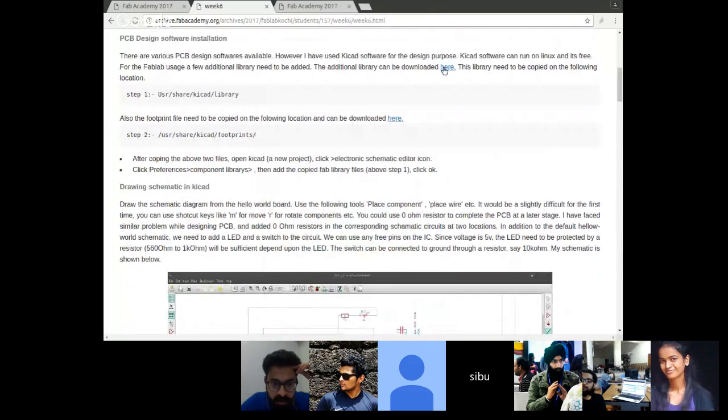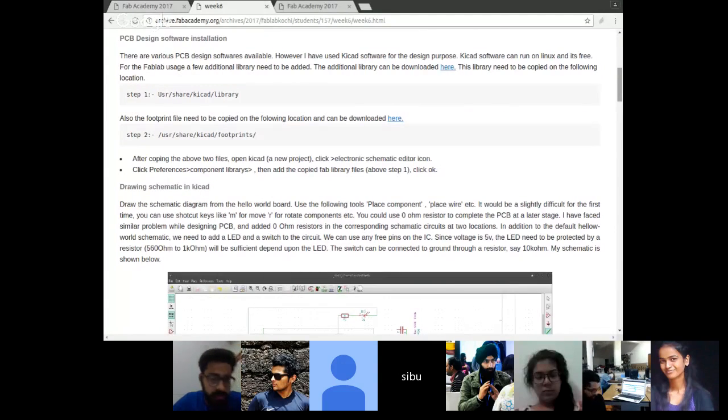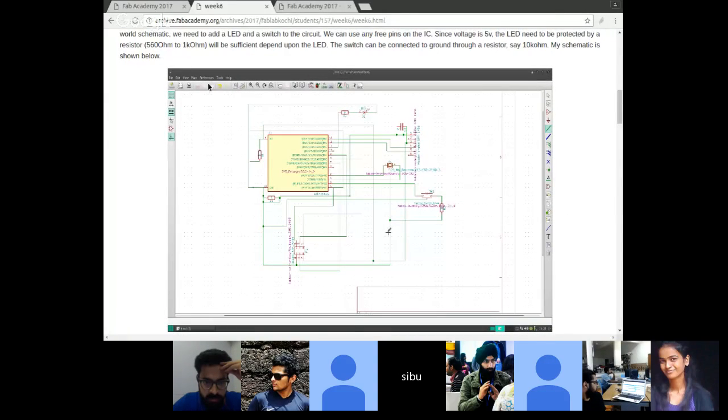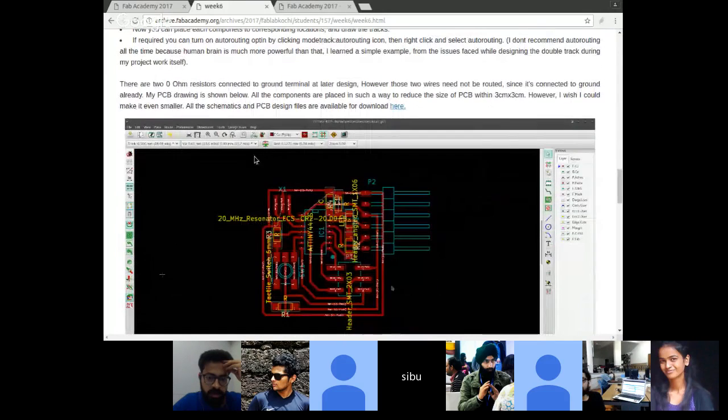And how are you taking DRC errors and all? Design rules. How are you taking them? Design rules. You can click it here. Then if you want, you can change the track widths. Everything is there. Okay, so even mention that. So what is the tolerance that you are adding? While checking the design rules, what are the parameters that you are putting there? And which is according to the bit size that we are using, right? Okay, I will add it. So I will add a screenshot of that DRC.